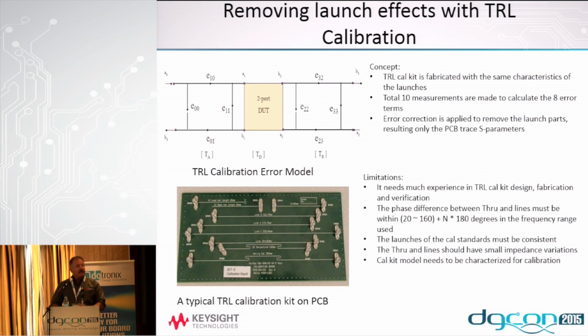And the error correction inside the test equipment for a VNA has couplers and switches that are very high frequency that need to be operating in both directions, transmission and reflection, very accurately. And so the TRL has been very good for the microwave world because the dielectric materials have been very consistent, shall we say. Ceramic or LTCC, there's other types of packaging, and there's only one net typically on a microwave circuit.